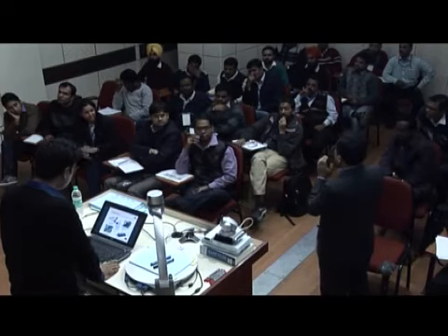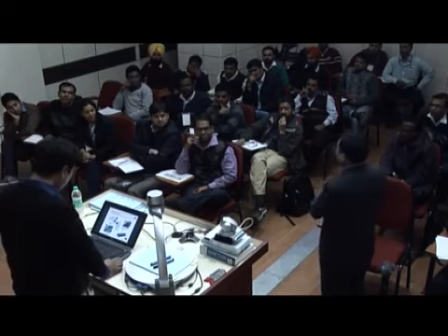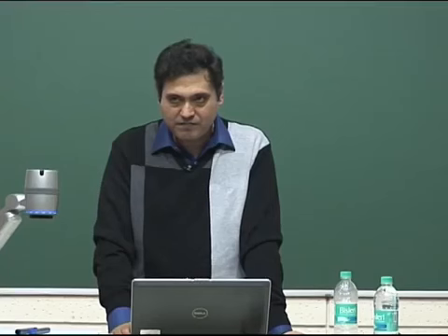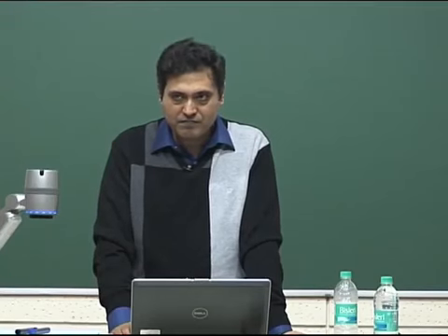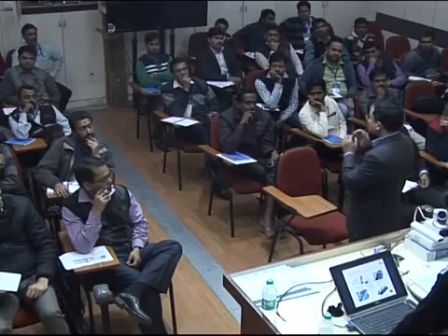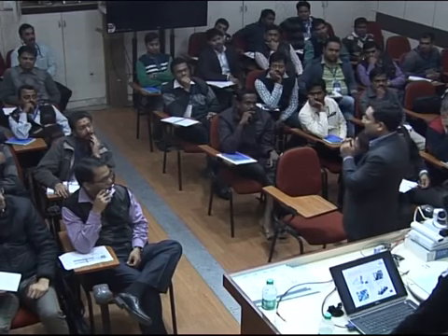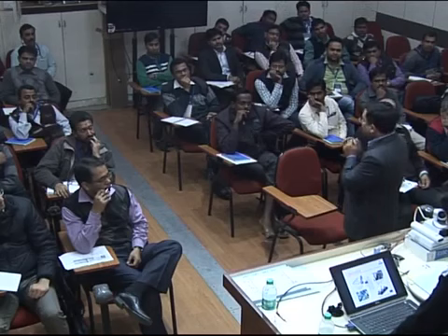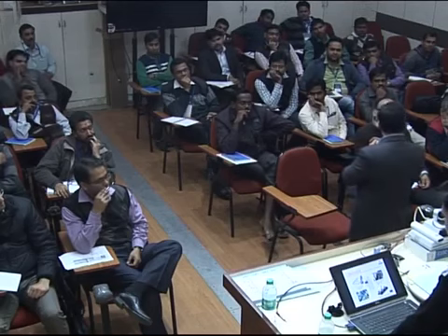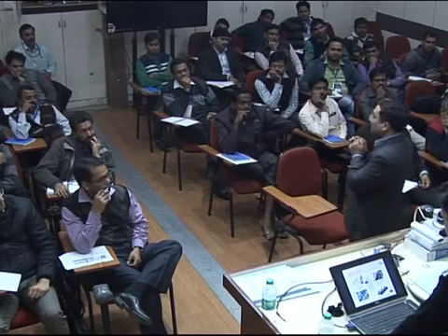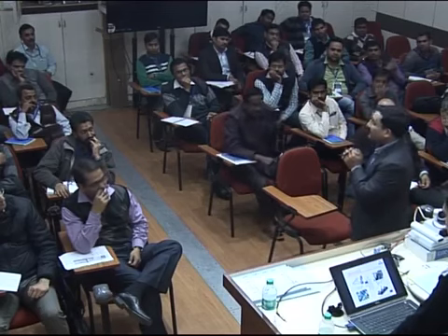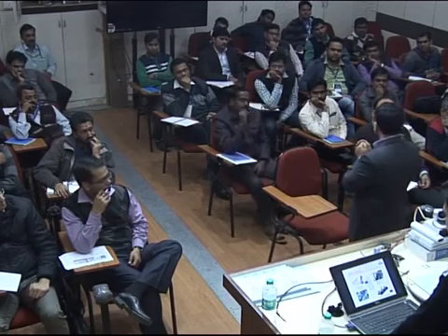So in such cases, fantastic, that is a very nice question. I really appreciate it. In inductive sensors, you will never be able to tune a sensor because the oscillation frequency, etc. are fixed. In 99% of capacitive sensors, you will be able to tune the capacitor to the media whose dielectric constant is having an effect.